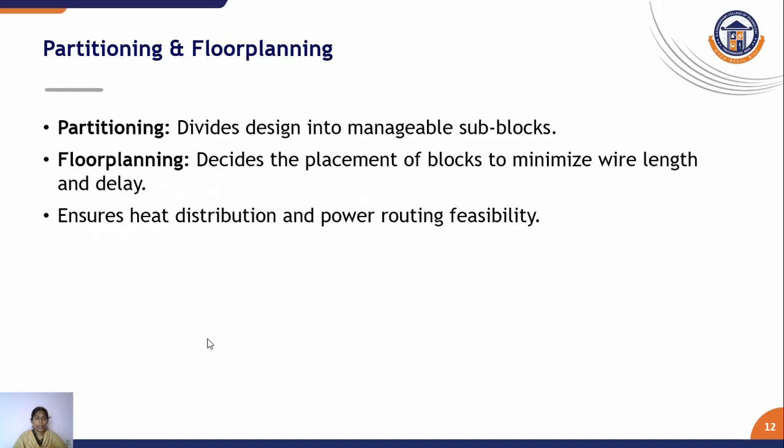Let's discuss them one by one. Partitioning and floor planning. Partitioning means we divide the design into manageable sub-blocks. After partitioning, we move to floor planning. Here we decide the placement of blocks to minimize wire length and delay, and ensure heat distribution and power routing feasibility.